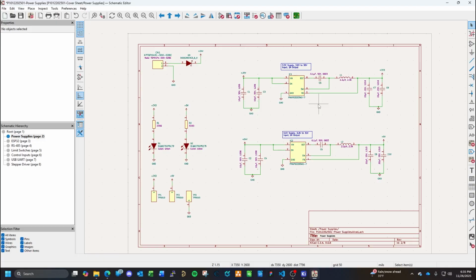If you're going to do things like that, you're better off doing it now before you translate it to a PCB. I know with the other software packages, the net becomes named. I don't know what the priority is, but the nets will share names like the 24 volt plus 24 volt, R2, R1. They'll be part of the net names, D2 and their connection points.